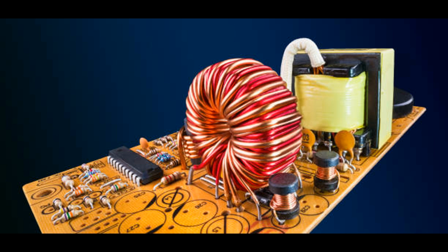Enhanced inductance. The increased flux density results in higher inductance for the coil. Inductance, L, is proportional to the magnetic flux linkage per unit of current. The core's high permeability allows the coil to link more flux for a given current, enhancing the inductor's ability to store energy. 4. Magnetic flux path.